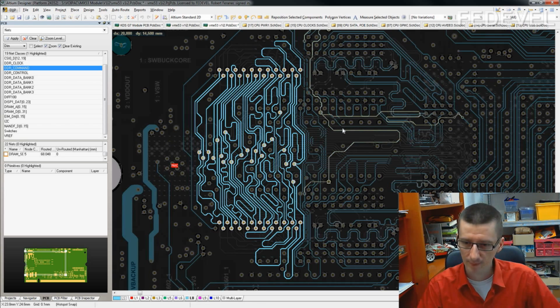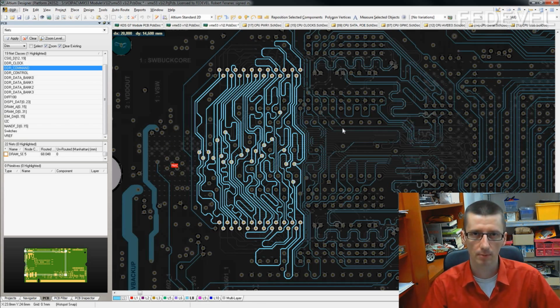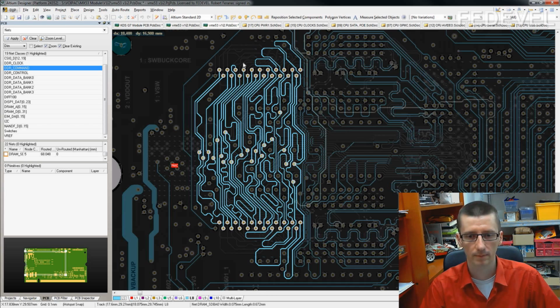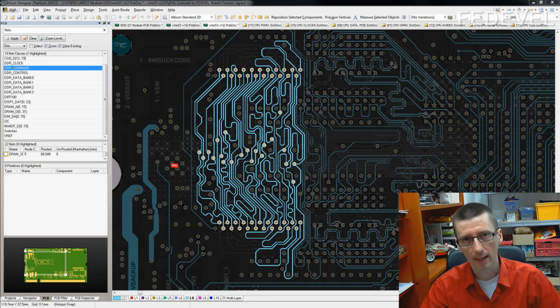And as I said, this is good practice. Use the same topology for the same buses, same signals in the same bus or same group. It's recommended in a lot of design guides, including Intel or AMD. It's very important for high-speed design. I use the length in via as an example of why to use the same topology for the same bus, same group, but that's not everything.